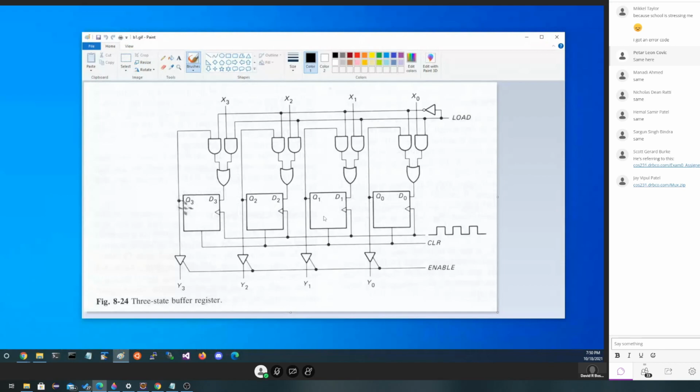At best, we would get some sort of a signal which might be halfway between a 0 or 1. So instead, externally to this, we're going to hook a tri-state buffer at each of these locations. Now, that circuit I showed you is one of these. So we would have 4 of them. Normally, they come 8 to the chip, but we would use 4 of them here. Notice here's the enable line.